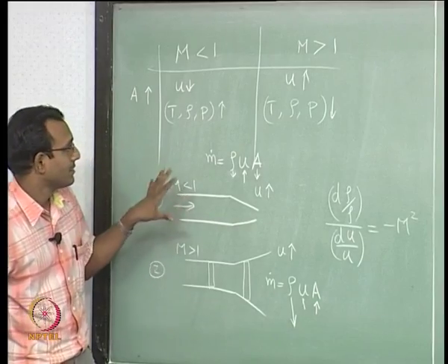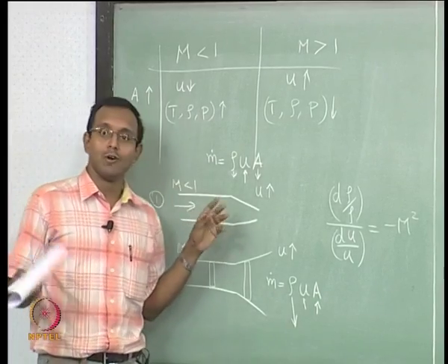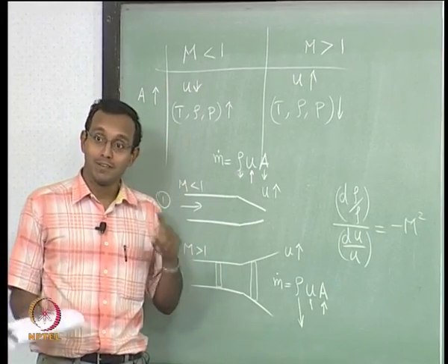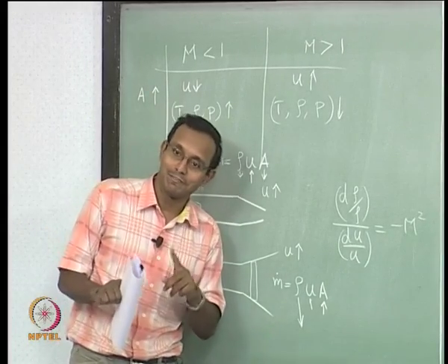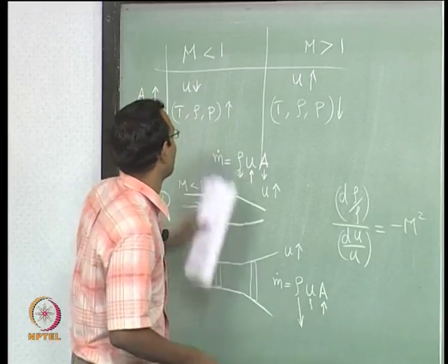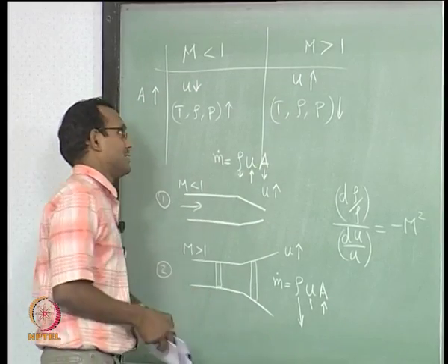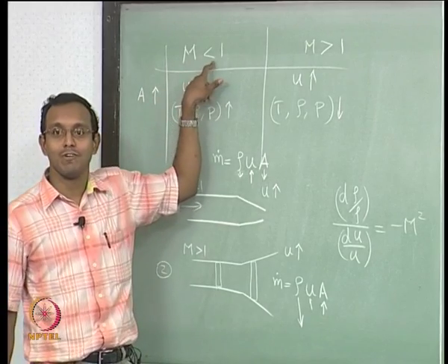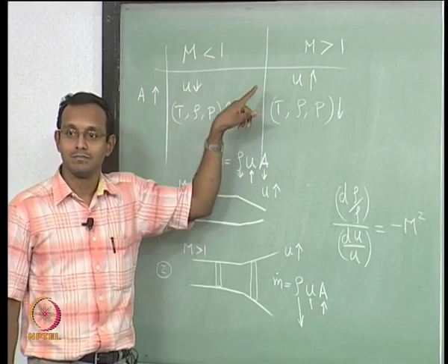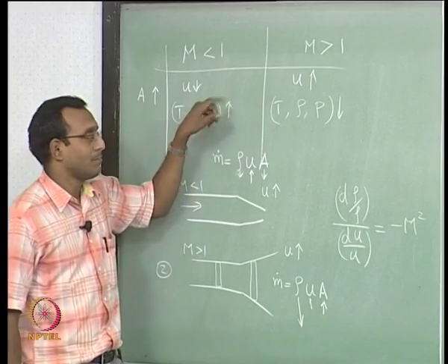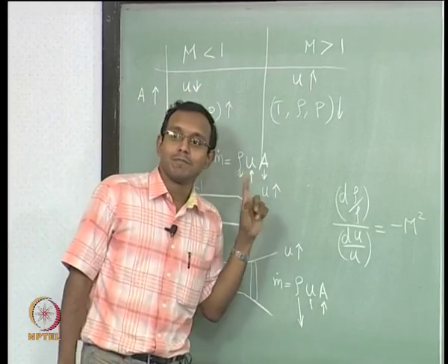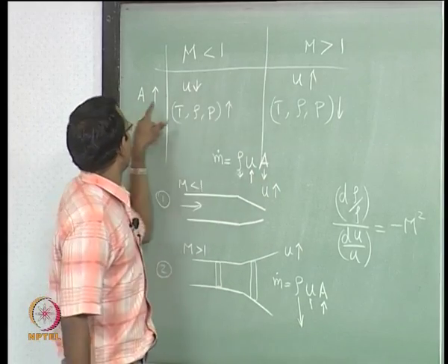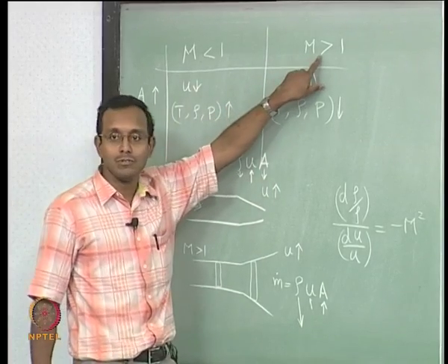Okay. Now, I hope you can explain things in CD nozzle why a nozzle should be that way, but there was one small gap which we never filled. Remember the last time when we were doing this whole table, we said I have to decrease area so that my Mach less than 1 flow will go close to Mach 1. Okay. But then I said if my Mach number is slightly more than 1, then I can increase area and accelerate the flow further to more supersonic.